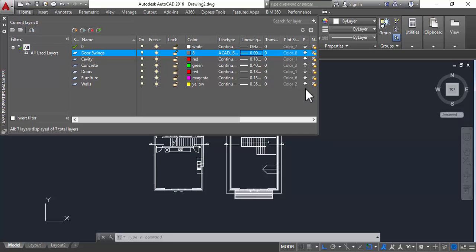But this one over here is quite important. I've had a lot of people tell me that they've set up their line weights and it's not printing. You then basically want to come back to this and make sure that that hasn't happened, because this is how you can either turn a line on or off to print. So if your lines look like that, those specific lines that you've made with these layer properties won't print. So you want to make sure that there's no no entry sign or whatever you call that sign on any of these print icons here.